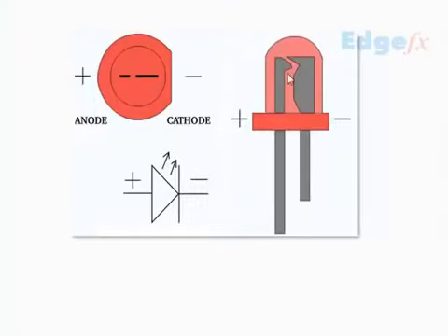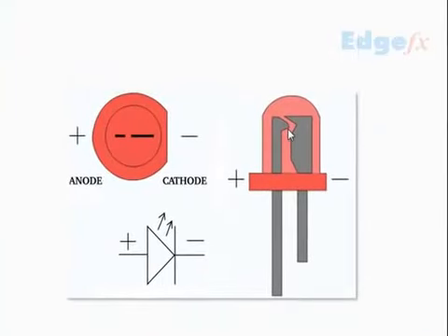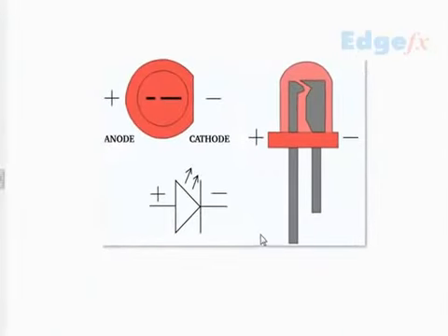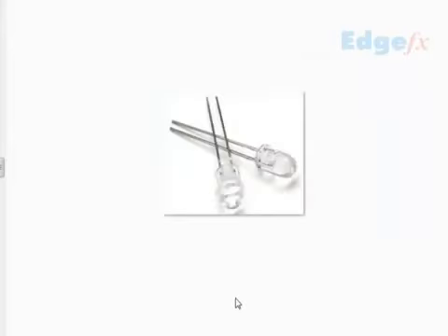At least some slight glow has to come, very slight glow has to come, and if it is not coming, be sure that the LED is defective. LED goes defective mostly because if the leg is short and then you apply more heat during the soldering. So be careful while handling the soldering for this active component, which is very sensitive to heat.